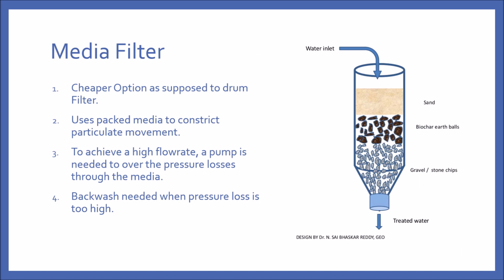We will now move on to the next part, which is utilizing media filters for suspended solid treatment. Number one, it is definitely cheaper as opposed to a drum filter. And the theory of operation is relatively simple, in which you pass the water filled with suspended solid through a packed bed media, which can be filled with sand. The way you distribute the sand can be done in different manners. You could use the coarser sand at the bottom, followed by the medium sand and the finer sand on the